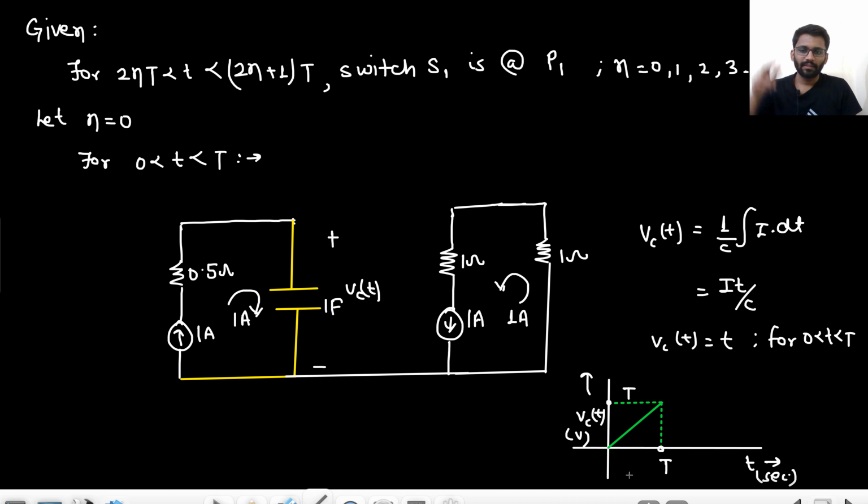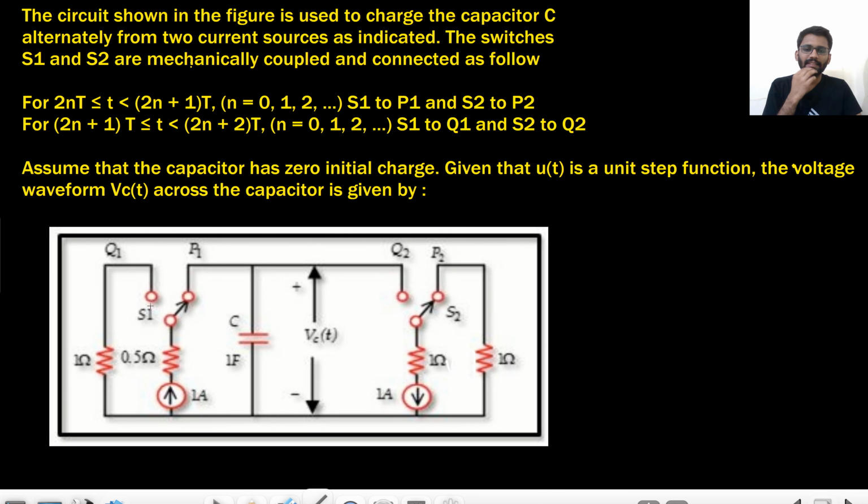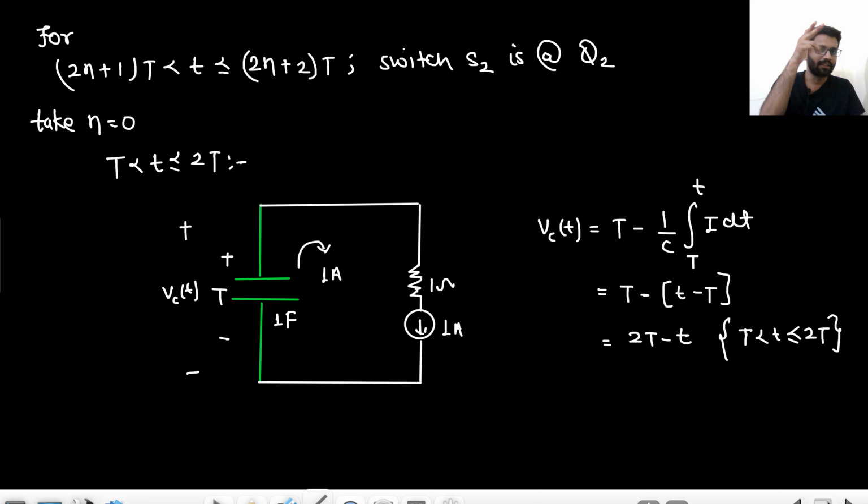First this 1 ampere current source was charging this capacitor. Now this 1 ampere current source is discharging the capacitor. We didn't make this condition because this 1 ampere current will be flowing through this network. So that's not really a matter of concern. Only the matter of concern is this 1 ampere current is discharging this capacitor. The same current was charging the capacitor, same current is discharging the capacitor. So whatever the voltage it has developed, the same voltage it will lose, right?